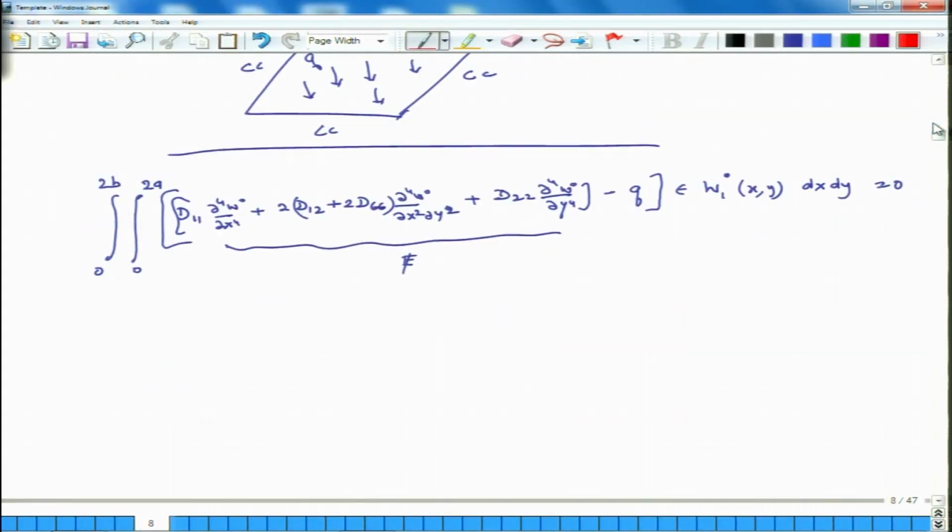So, when we do this integral, W is a function of w11 times 1 minus cosine and 1 minus cosine y over all that. So, as I do the integral, x, y, they will go away, because I integrate over x and y. So, the only unknown in this equation will be w11, and then I can solve for w11 and get the solution, and that will be an approximate solution. So, this is the overall principle of virtual work.